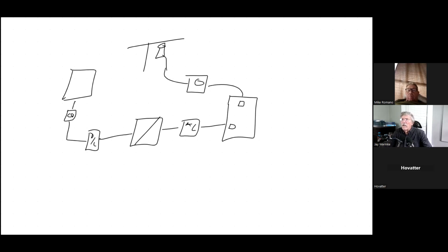So how does power flow through this system? Well, if I turn on a load over here, it's going to pull power from wherever it's available. If the sun is shining, the first place it's going to pull it from is the array, because it pulls power from the closest source. In this case, that's going to be the array. So the array is going to draw power through, and it's going to go all the way to the load from the array, going through the inverter.